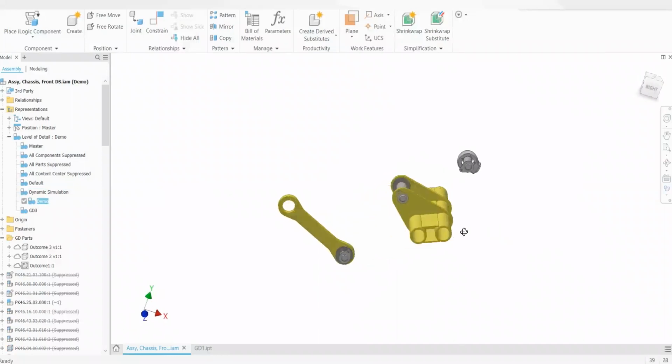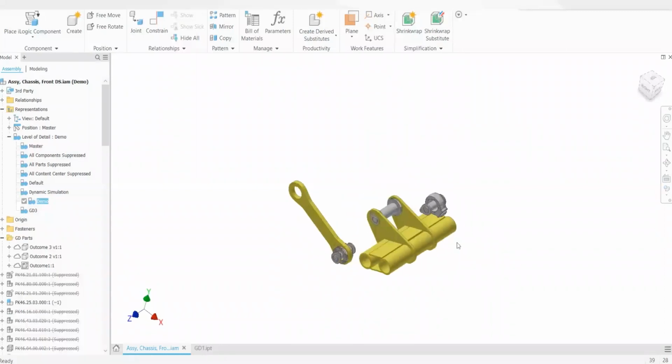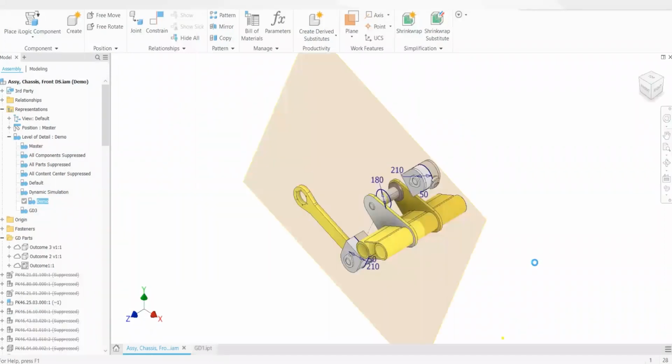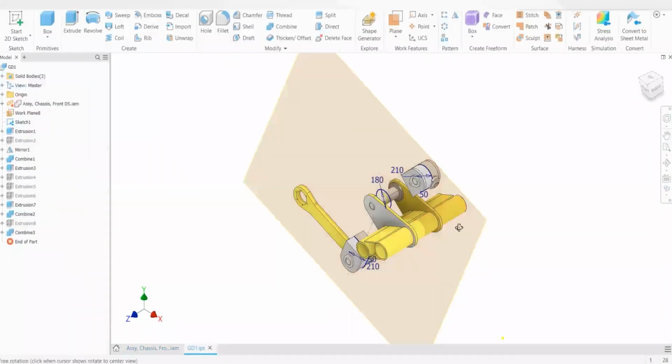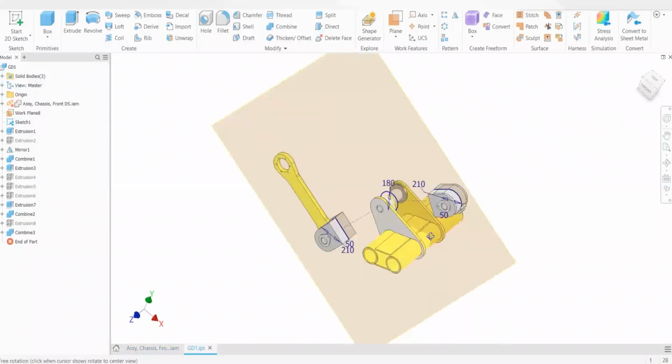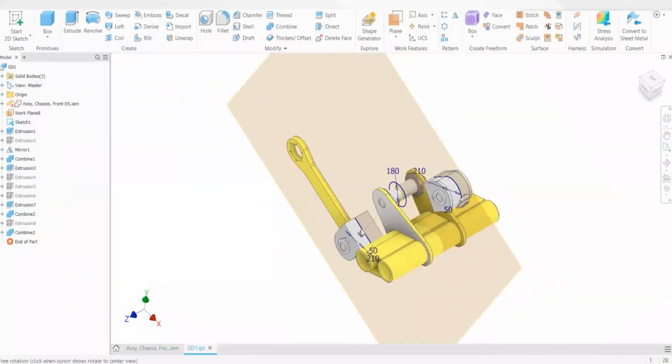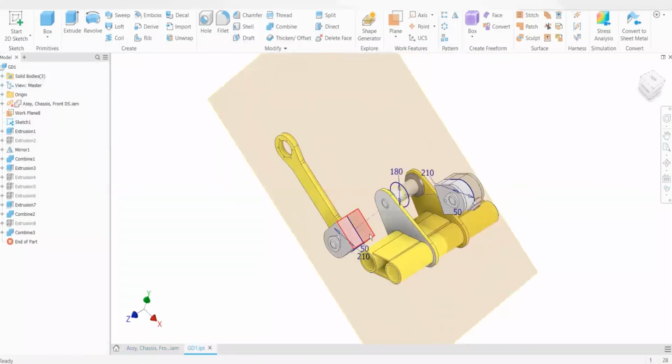And now we can use this to build the necessary geometry we require to work with generative design. What is that necessary geometry? It's going to be the obstacle geometry as to avoid collisions, as well as the key features, so the preserved geometry that generative design will use to build the part. From the step, once it's been isolated, we simply have to translate this information into a new part file. This is done by using derived. Once we derived it, it's taken into the new part file, and we can start making any additional changes or features that we may require to perform the generative design process.